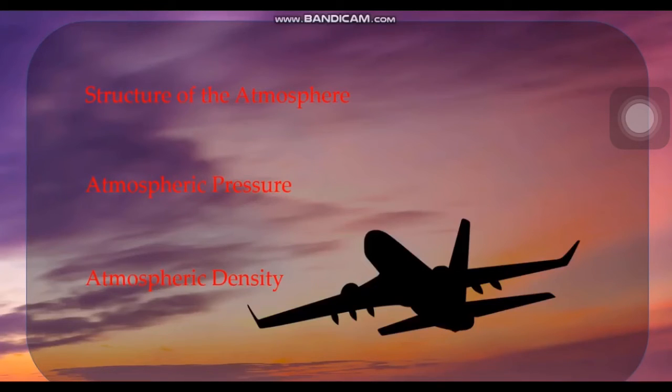The last one is atmospheric density. The density of the air has significant effects on aircraft performance. As air becomes less dense, it reduces power because the engine takes in less air. Next is thrust, because a propeller is less efficient in thin air. The last one is lift, because the thin air exerts less force on the airfoils.